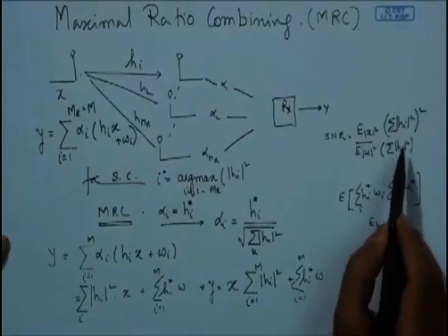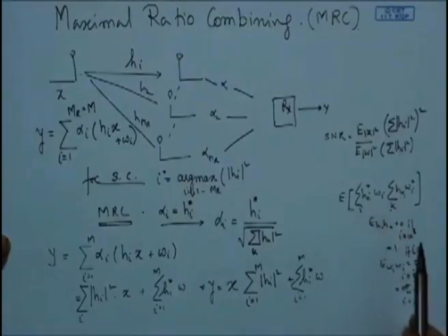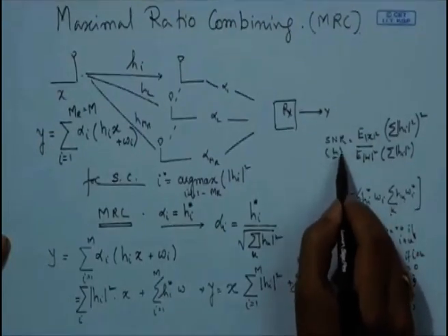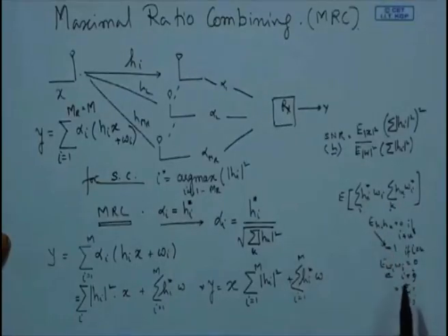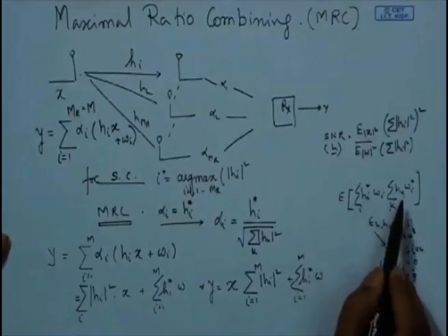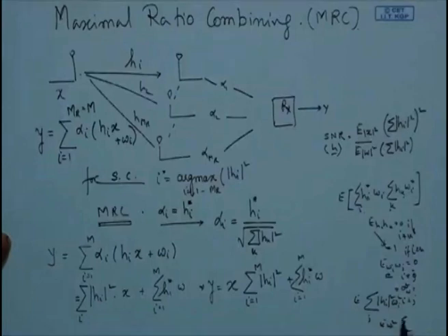So going by that, the power is going to be added up only when hi is equal to hk, that means i is equal to k, and since this is a function of h, this is dependent on h, we do not actually operate the E on h, so this particular part does not take into effect, only this comes into effect. So we have the hi hk part, and since E of wi wj is equal to 0 for i not equal to j, we basically have sum over i mod hi squared and an expectation operator, this E comes inside, E of wi squared, so E of w squared times this summation, that is the expression that we have over here. And in the numerator, in a similar manner, we have the square of this.